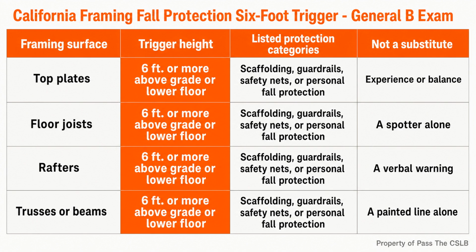First, identify the product. I-joist, laminated veneer lumber, glulam, rim board, truss, and solid-sawn lumber are not interchangeable labels. Second, identify the controlling authority. For an engineered alteration, that is the manufacturer's published recommendation, or a design that specifically considers the alteration. Third, protect the flange. On an I-joist, no cut and no notch belongs in the top or bottom flange. Fourth, verify the web opening. Size, location, spacing, support distance, member depth, and product series all matter.